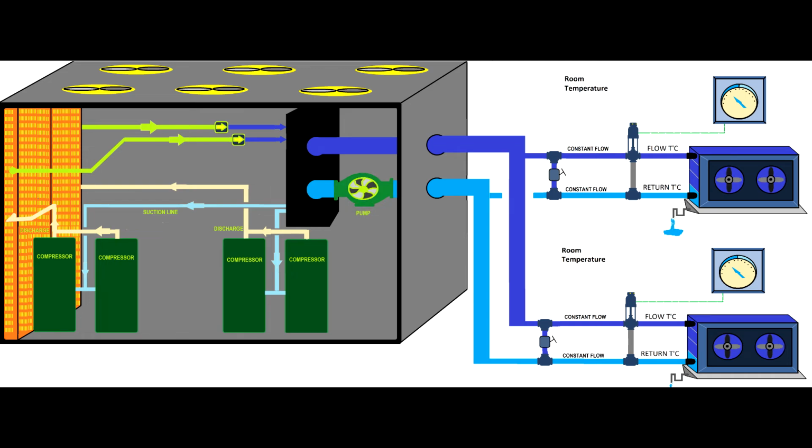And when the air circulates through a very cold heat exchanger, the moisture drops and falls onto the drip tray, and it will be eliminated by the drain. As you will see, a little bit of water going out of the drain. So this is the process.